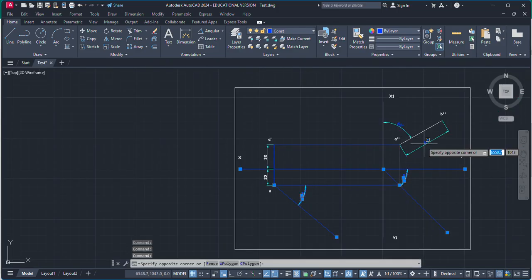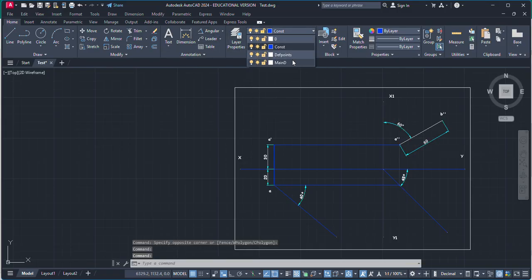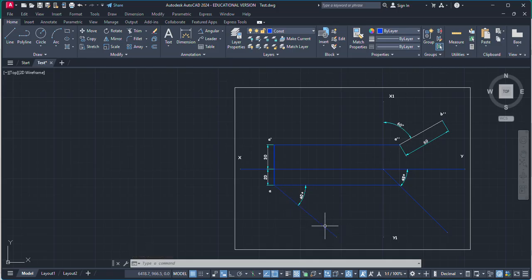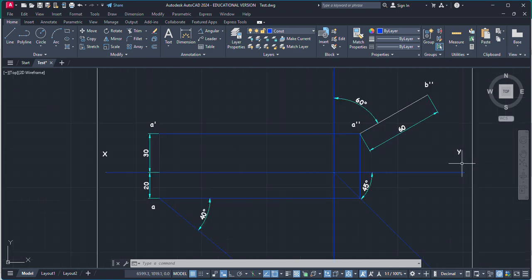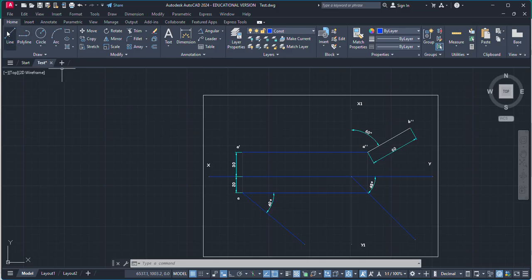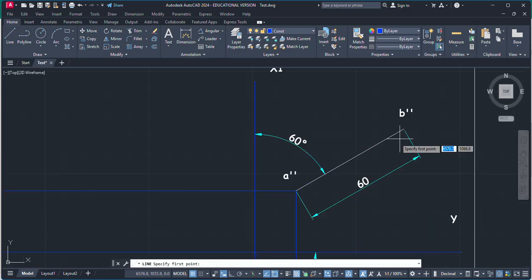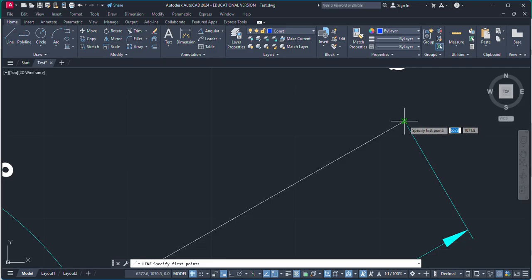We have side view, we have projection of point A, and we have true line in the top view which is at 40 degree, but the length is not fixed. So we need to find the length. Here we need to find the length. We do have the angle, but we do not have this length. So let's start with, from these given conditions, what we can do is, from this point B, which is the side view, I'm going to draw a locus.